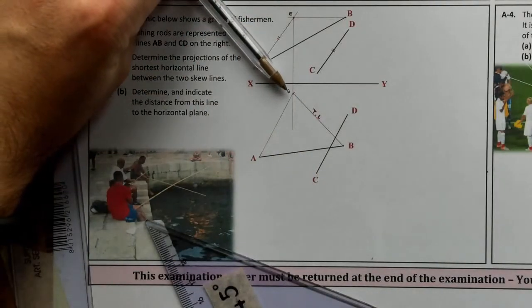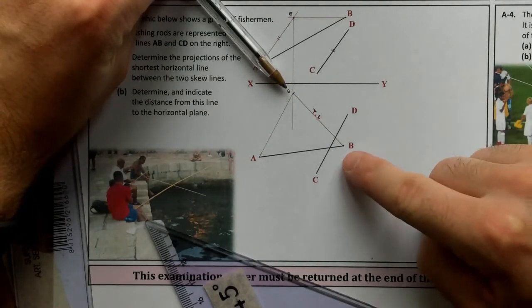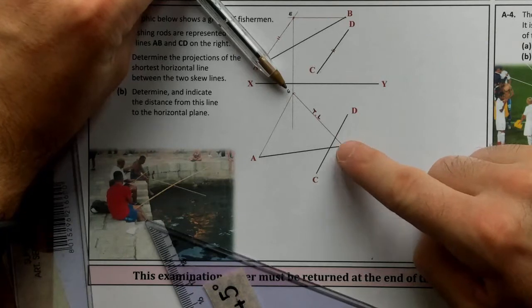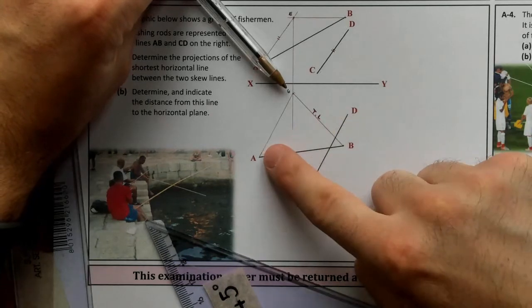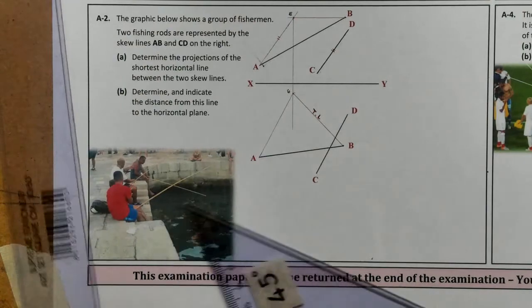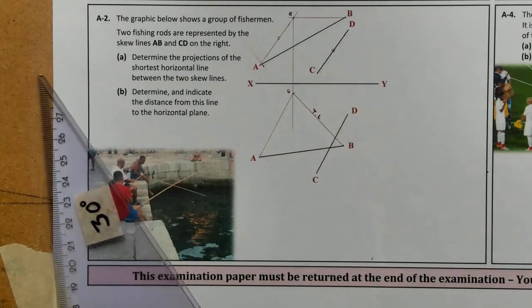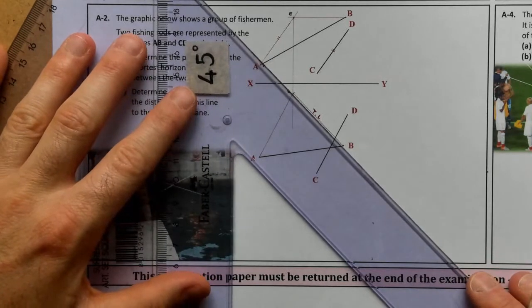So what we're actually going to do now is we're going to look along the true length, okay, set up an x1, y1 perpendicular to it, okay, and looking along the true length, we're actually going to see that true length, the line from E to B, as a point view, but that means we're actually going to see the line A to B as an edge view, okay, and therefore we'll also get C to D then as well. Alright, so setting up an x1, y1 perpendicular to my true length.